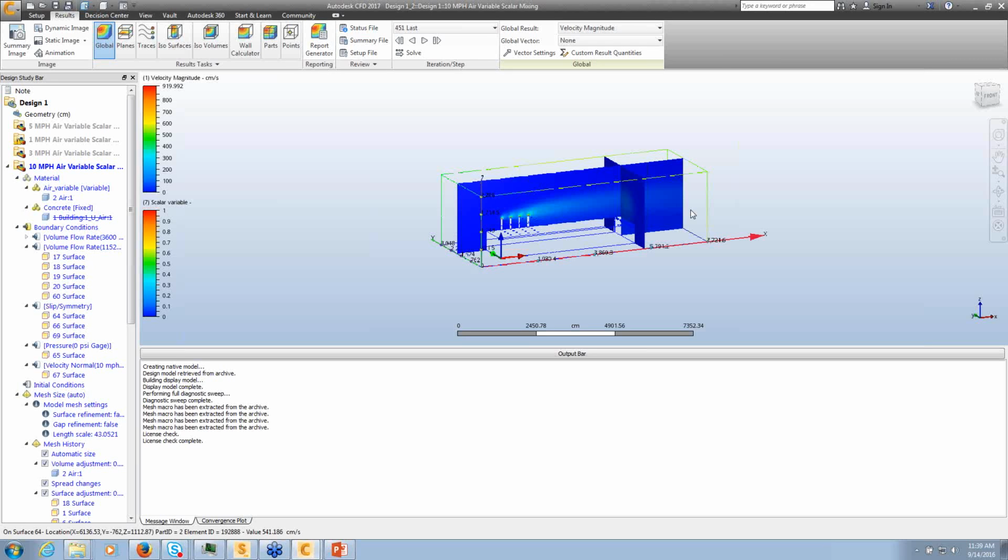Yeah, exactly, to have an idea of your end goal of the simulation you're running. Or even sometimes you don't have an idea about what the size of the air domain should be. So when running the simulation, you're going to say, okay, this is preventing a good circulation of the flow, so let's make it bigger.